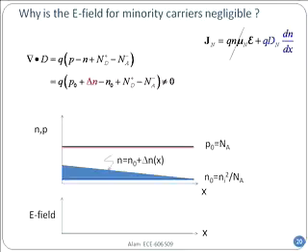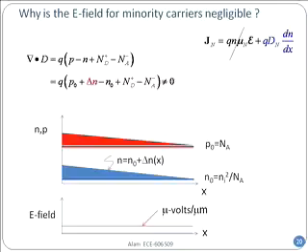So what it is going to do as a result is it will increase the electric field a little bit in that region, a very tiny amount, and it will pull in holes from the contacts to almost exactly compensate the electron concentration. So it's not photo-generated. It is coming in because it wants to minimize that quantity on the right-hand side. So it will pull in a little bit of holes to sort of match the profile.